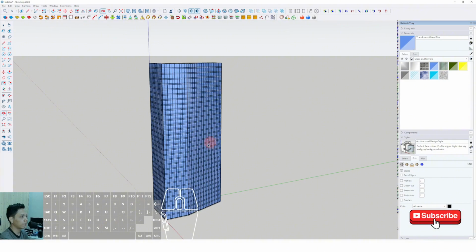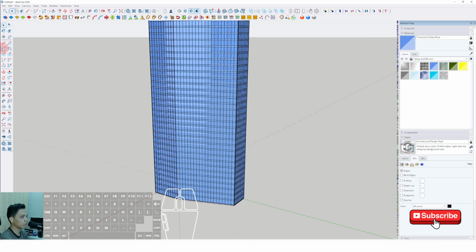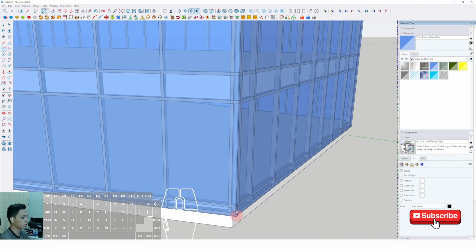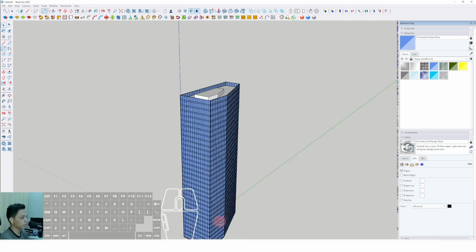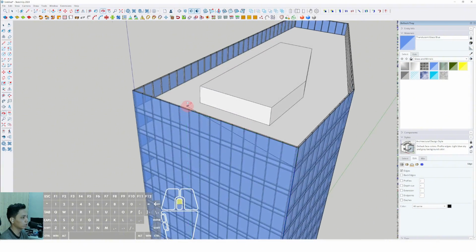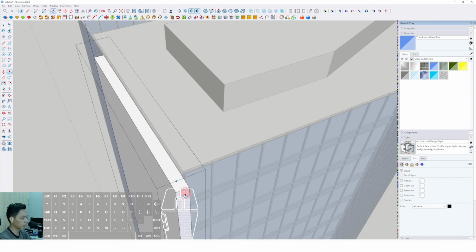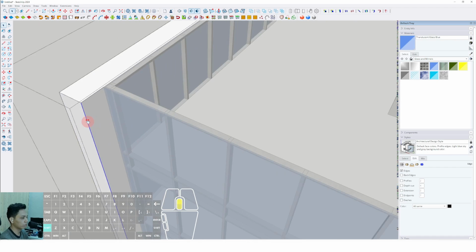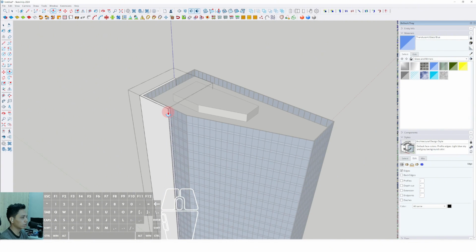We can use the aluminum composite panel. We can use the rectangle, click from this position until the another position. I think we can make the aluminum from this corner to this another corner to this another surfaces. Push it to front around 1 meter. Triple click, right click and make group, and then we can push it again around 1 meter and make the duplication of this line and push it to the another position.